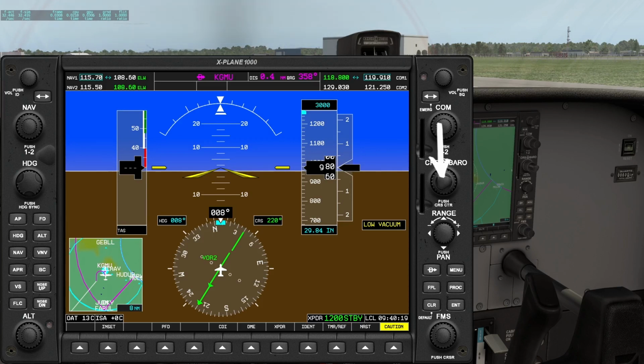We can also turn the smaller knob, and it will turn the HSI to whatever heading you need it to turn to. So then to fly direct, when we take off the runway, we'd fly heading 220 in our course. That would take us direct to the ELW VOR.